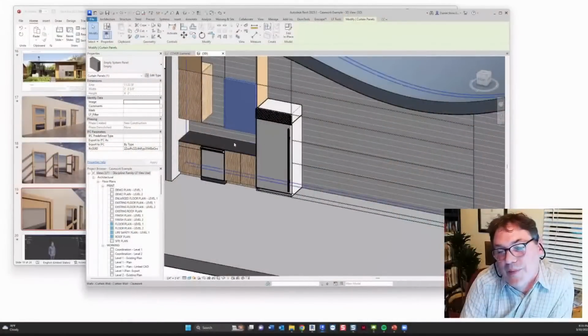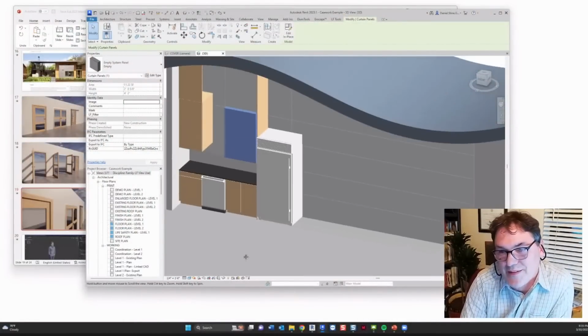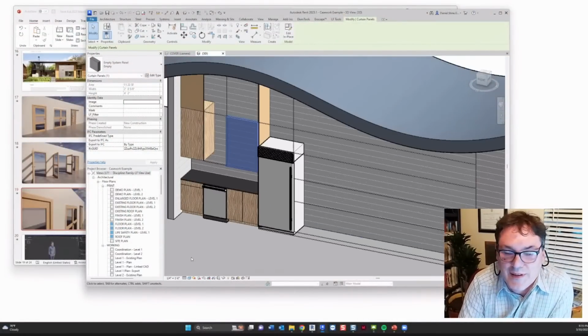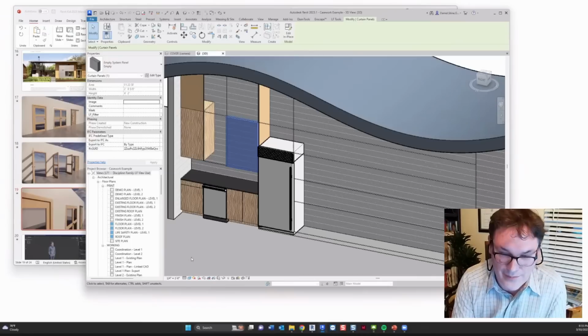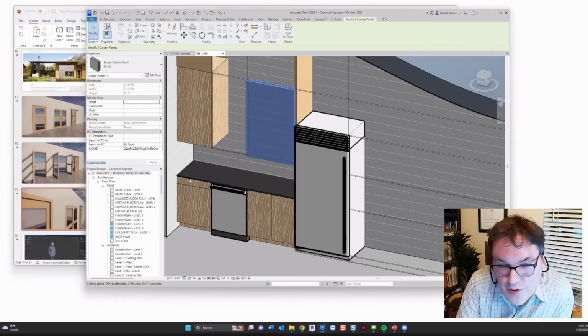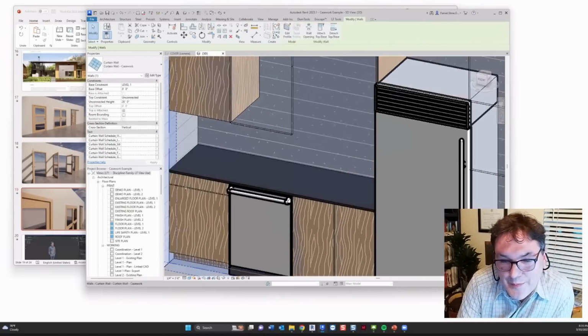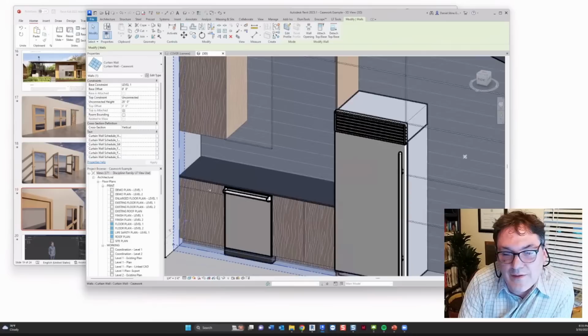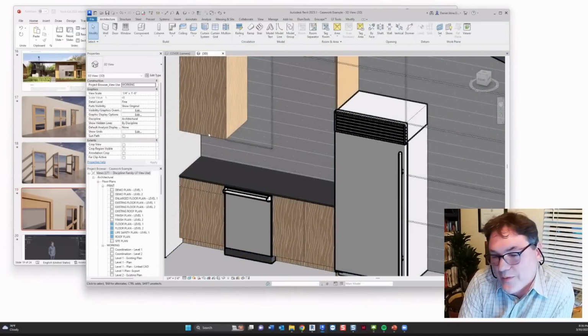The positive or the benefit to this is just how flexible it is. We're almost always designing custom casework, right? So this allows us to slice it up. Like this drawer plate is defined by the fact that a curtain grid was added there. So that drawer height can be any height it wants, and it can stop anywhere we want it to.